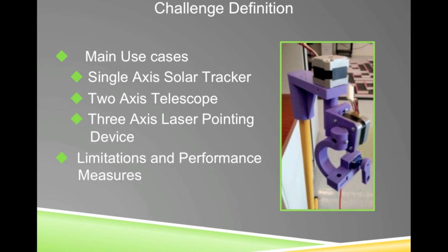We've never controlled multiple types of motors simultaneously before, and this is one feature that the telescope required because celestial objects move relative to the observer. So we would have to take into consideration how far the object moved while one of the motors was moving the telescope. So one performance measure that we implemented was to see if we actually were tracking a specified celestial object during the movement of the device. In order to ensure that we were, we plan on integrating a camera into the system to have visual confirmation of the current position of the telescope in relation to the celestial object.